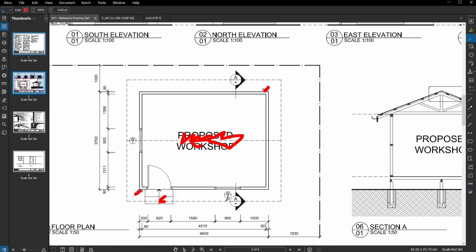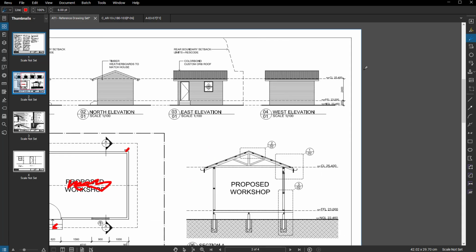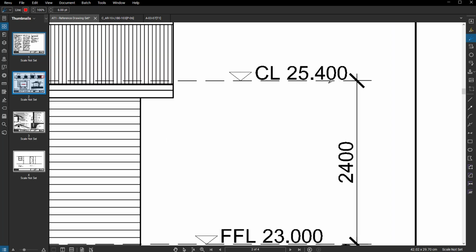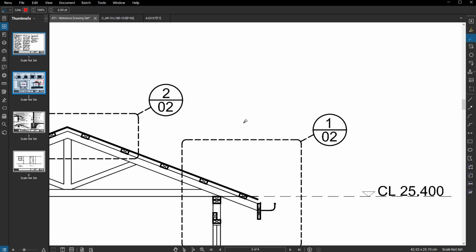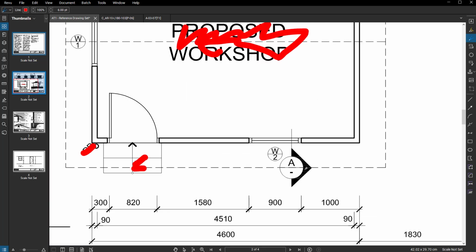So this goes hand in hand with my next point, which is around symbols in the drawing. Such as these symbols here, these callouts, or the section marker or the window markers. To be honest, there are two different ways you can do it in AutoCAD. One is through a dynamic block, which means that essentially you can type in different information into that object every single time, which is the way that the title block is done. The same way you can double click on a piece of text and it will update dynamically. The other option is to do it straight up manually, and that's the mode that we're going to do here, just so you can go through the motions of how to create these objects and shapes.